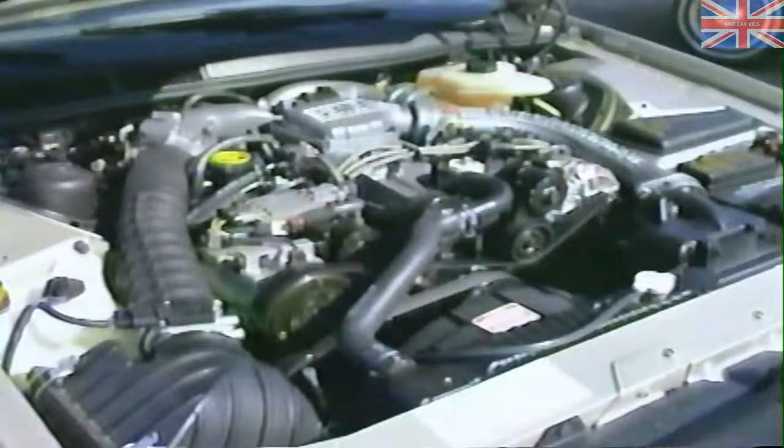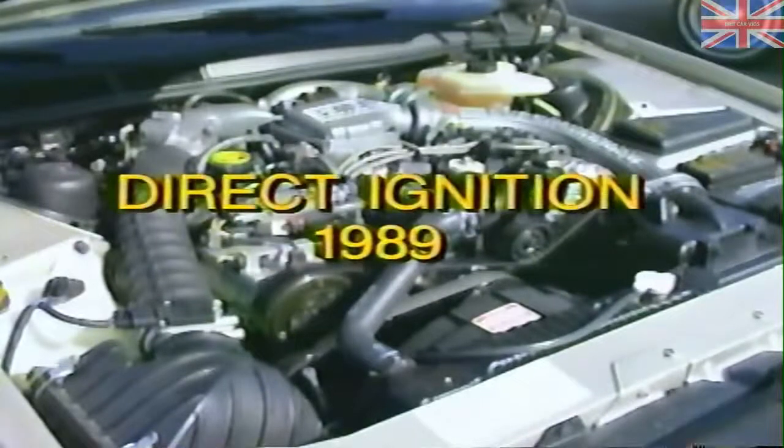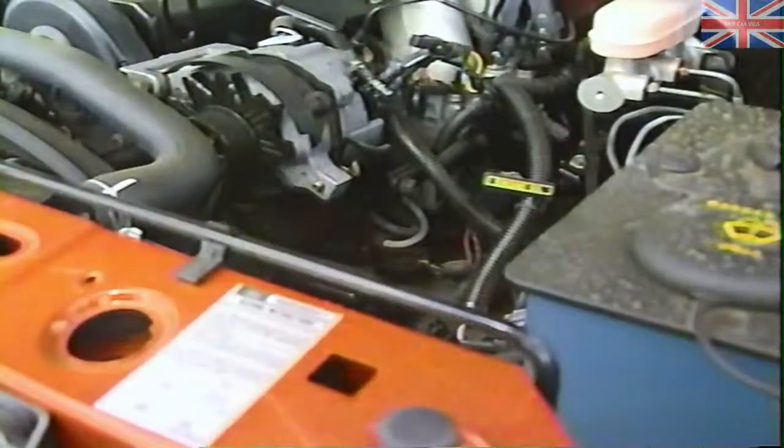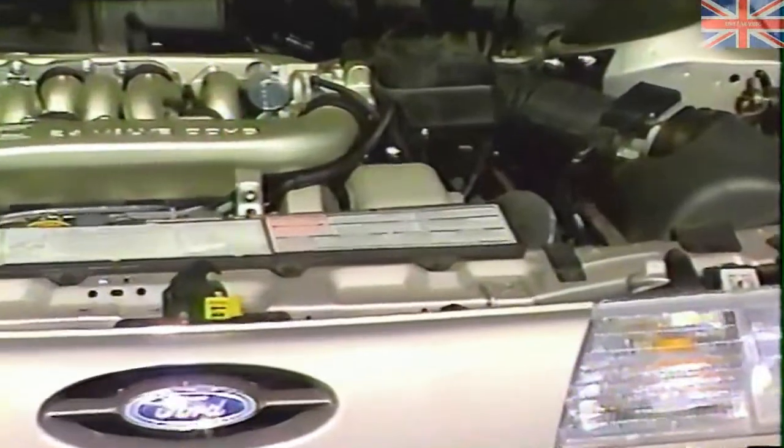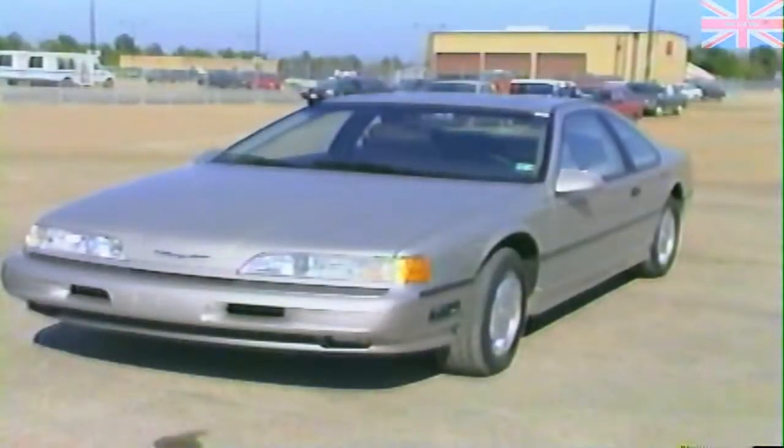One last piece of information we should introduce prior to diagnosing some on-vehicle problems is that in 1989, Ford introduced a direct ignition system. Direct ignition is utilized on the twin spark plug 4-cylinder Ranger engine, also on the 3-liter dual overhead cam SHO Taurus engine, and on the supercharged 3.8-liter Thunderbird and Cougar models.